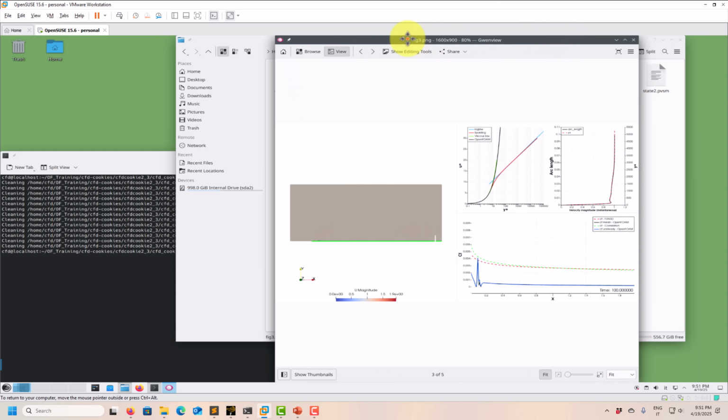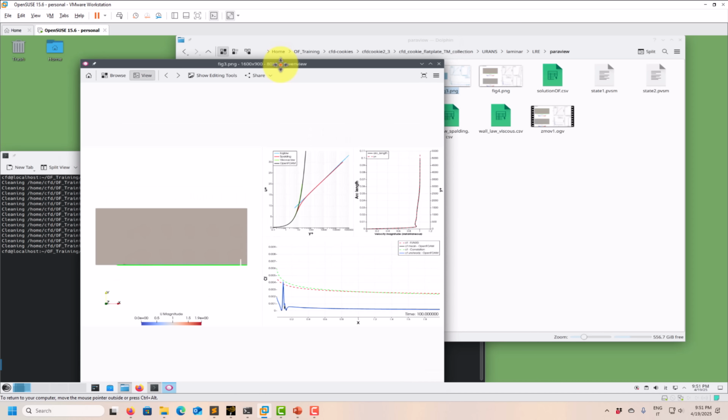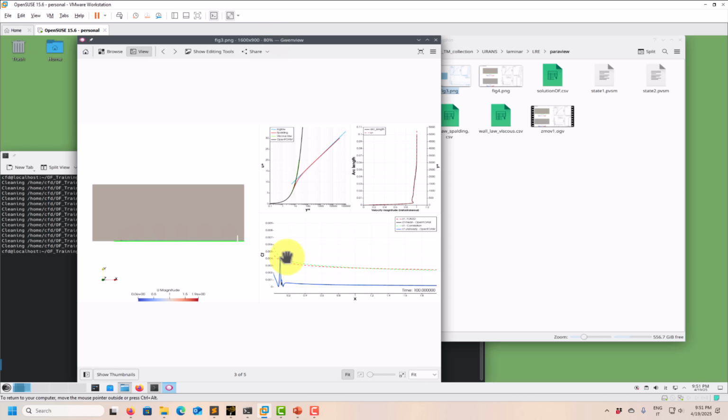As you followed in the previous steady tutorials, in Fig 3 we have the friction coefficient, and we can use this to validate. As expected, Laminar will highly under-predict the friction coefficient. You have it here, and very interesting, look at the matching that you have here with the theoretical viscous law. But this result is completely wrong. This velocity profile is also wrong.